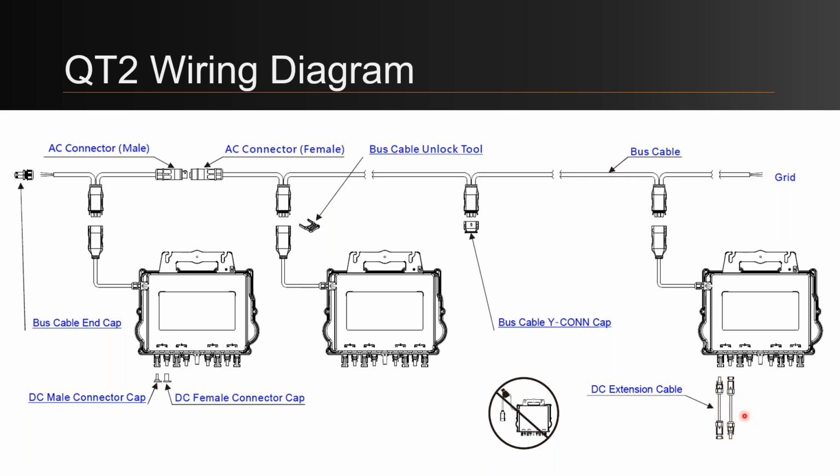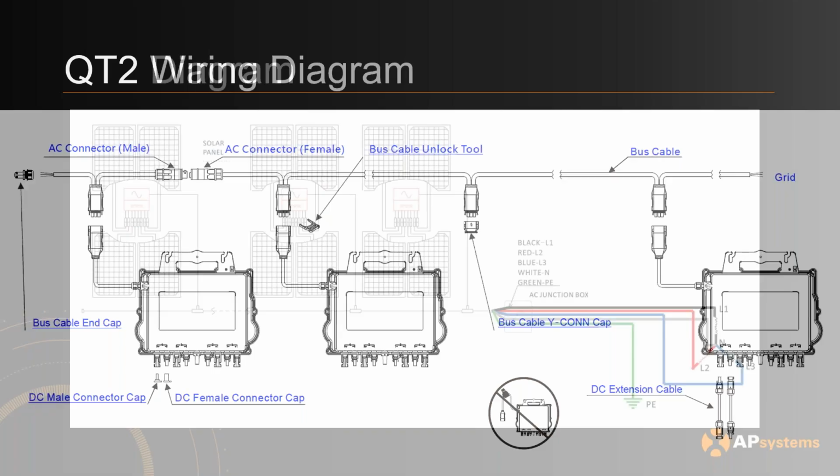One thing I'll also mention is, in general, don't hold on to the microinverters like a dead chicken by the AC cable, because it strains the gland. One of our tech support agents said that these inverters kind of look like purses, so you ideally want to hold them by the handle of the purse. I don't know if you want to use that metaphor, but that's one way to think about it.